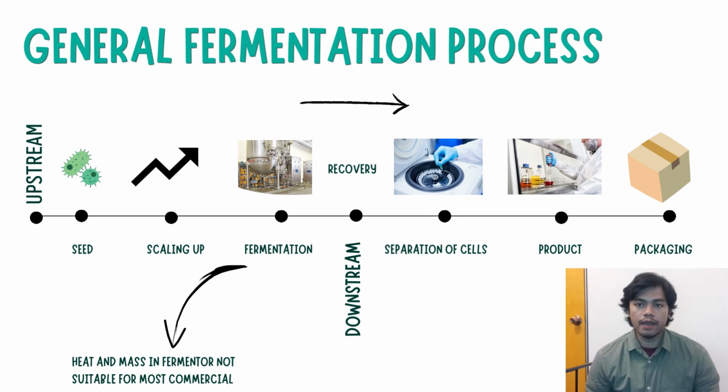But heat and mass transfer in fermenters are often achieved by an intense mechanical agitation to disperse air and to promote adequate mixing. This shearing action of rotating impellers tends to damage the cells, for example microbial strains whose morphology is significantly affected by it.